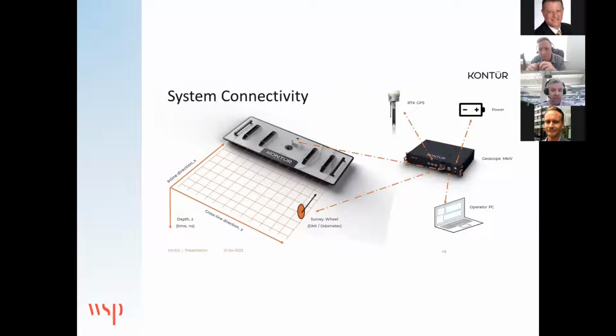I was on a job in Orkney in Scotland, and it's so frustrating. Halfway across this bridge, in the middle of nowhere, the system I was using had no 3D data. The GPS data just stopped working, because it was so reliant on the mobile phone signal. So we got halfway across the bridge, and it stopped working. Thankfully, the survey wheel helped us with that one. So it's a great system, really simple, very powerful into the PC and in the processing. And as I said, the processing of this software is undertaken through their Examiner system.